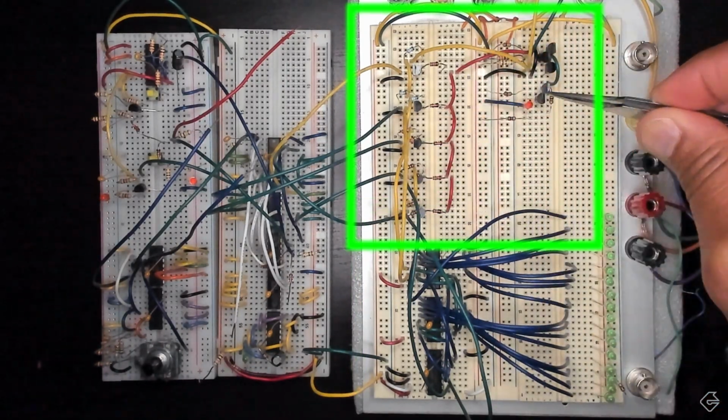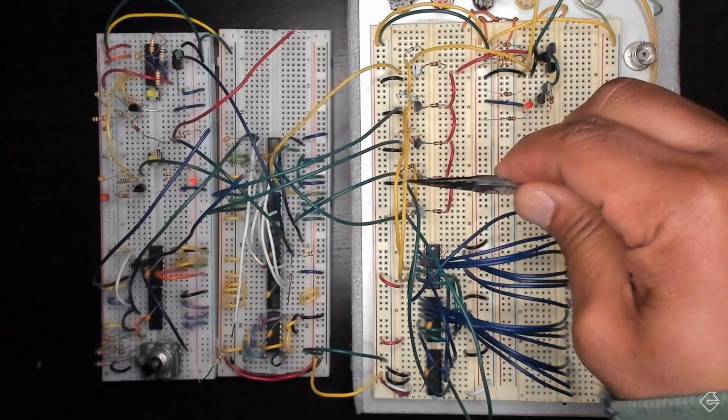And the driver at the top right, the driver that we have right now, will control a single set, in this case 3 high power LEDs, that run on 12 volts and can range between 0 and 350 milliamps. That's what we've created here. But the way we've designed it, we can actually daisy chain a number of these drivers together so we can control more LEDs. They're all going to be at the same intensity, of course, but this is really neat. And we're only limited by maybe the physical characteristics, so how big this board is going to be.